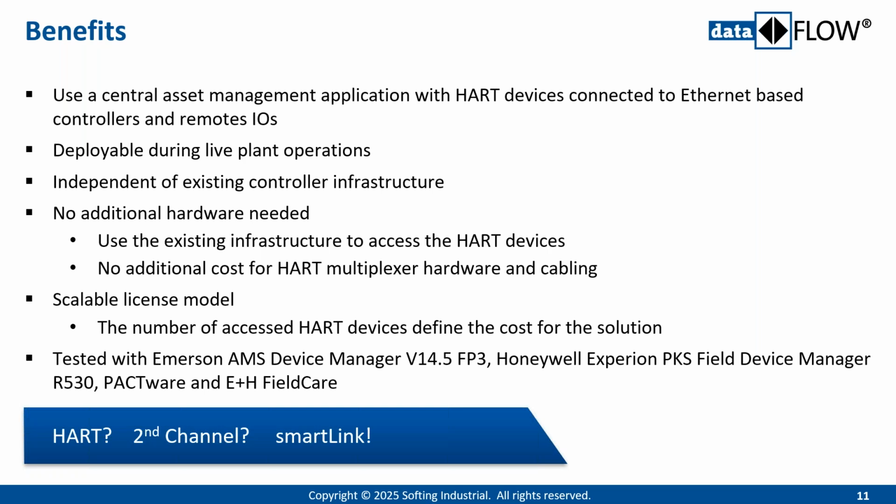It's independent from the existing controllers, so we don't use controllers to do the communication. The communication is really done directly with the remote IOs, with the CFU to the HART devices. If you compare it with other solutions which are typically using HART multiplexers, the big advantage with our solution is you don't need additional hardware. So you're using the existing infrastructure to get access to the HART devices, and you don't have additional costs for HART multiplexer hardware and cabling.